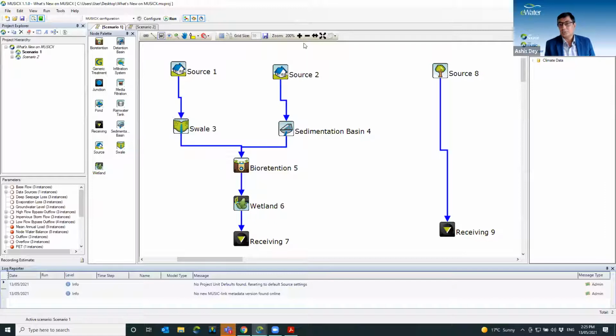But through MUSICnet, you can have many different types of land use type, maybe 5, 6 different land use types, different types of development site like residential, commercial, and different councils are basically assessing what parameters will be suitable for them, and they are putting in their values. So like we have 16 different councils, they are all different. But what we're using as default is based on the New South Wales MUSIC modelling guideline.